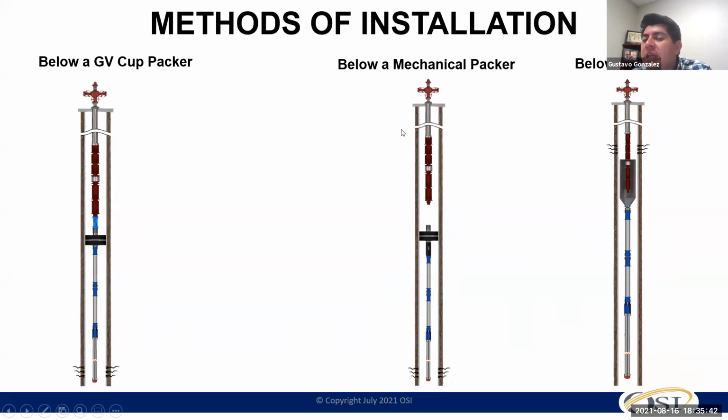So you can pull that ESP back at any time without pulling the sand control management that you have underneath it. Or if you're doing an amazing job and you're able to control this without affecting the inflow, you can maybe, after you deplete this well, go back with the rod pump, and you already have the sand control system underneath it.